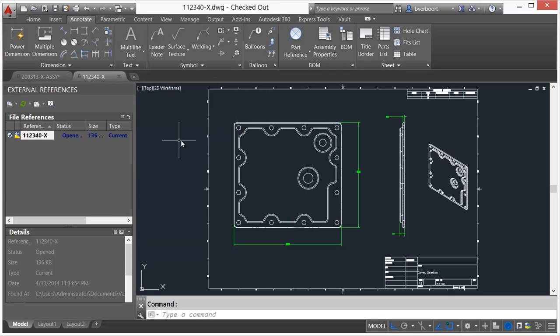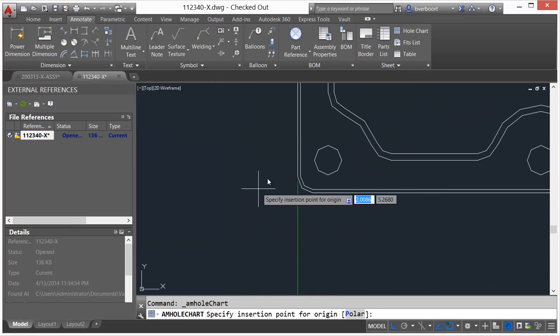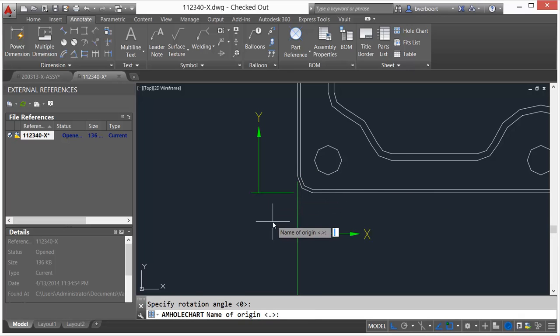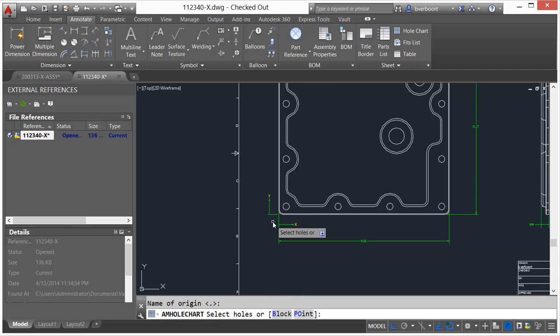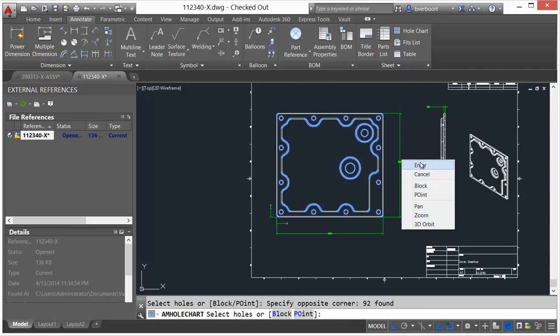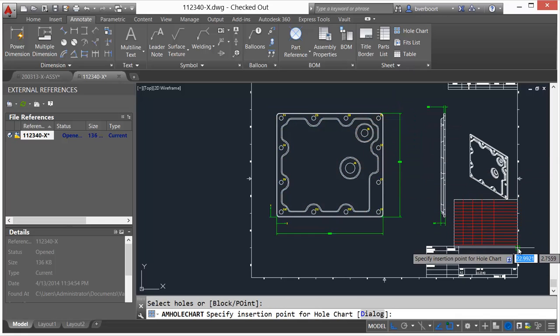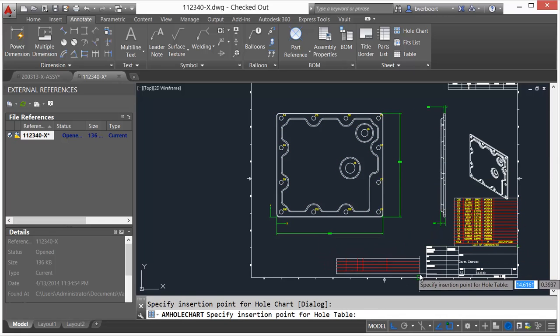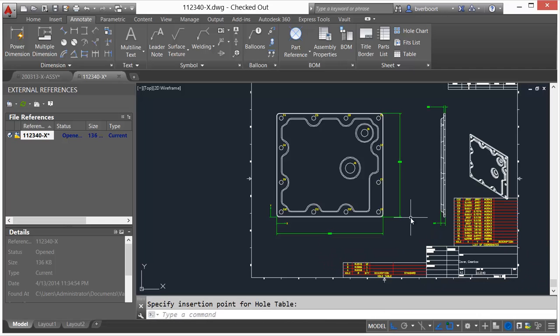Checking out a file creates a new version of the document, which is stored in the Vault and captures the history of change over time. File version history can be reviewed and even restored if required. Once edits are complete, the file is saved and checked back in, committing the new version of the document into Vault.